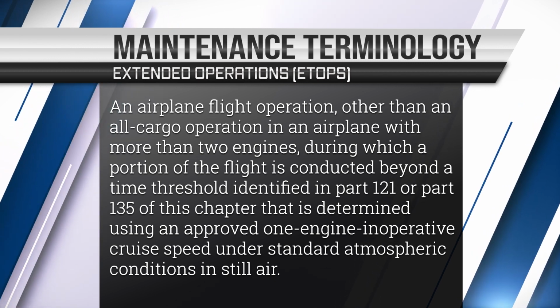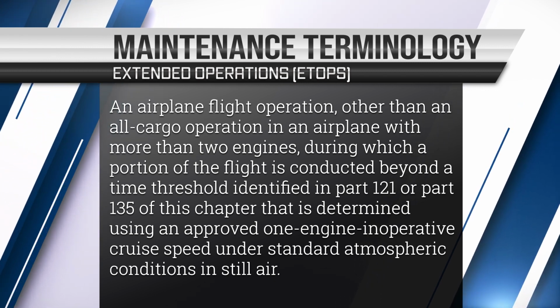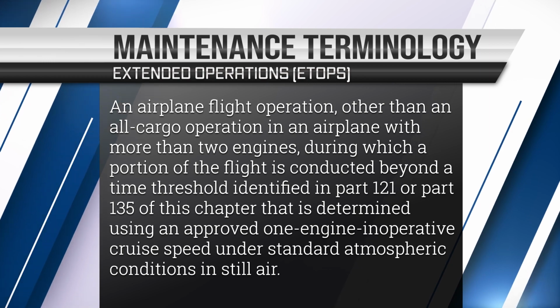It means an airplane flight operation other than an all-cargo operation in an airplane with more than 2 engines, during which the portion of the flight is conducted beyond the time threshold identified in Part 121 or Part 135 of this chapter, that is determined using an approved 1-engine inoperative cruise speed under standard atmospheric conditions in still air.